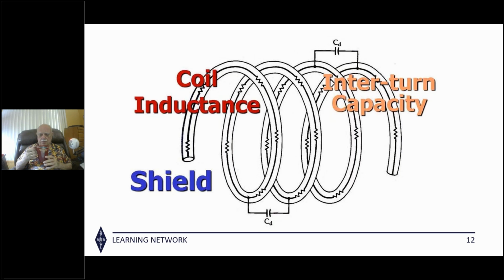Okay, next. I read somewhere that it is important not to let the first and last coils touch when doing an open zip tie coil. Is this a legitimate concern? Yeah, that's a reasonable idea. I think that's principally due to arcing, because if doing this coiled balun like that, the impedance is going to be pretty high at the end. So I think that's a good recommendation. Keep the ends of the coiled balun separated by a distance.